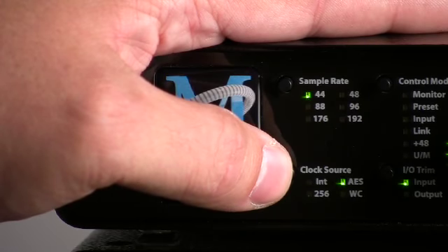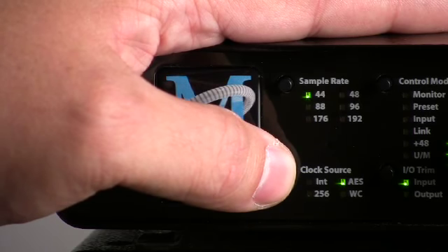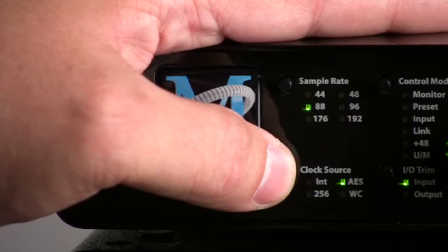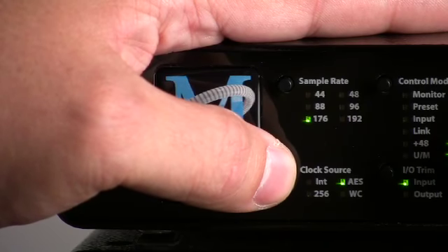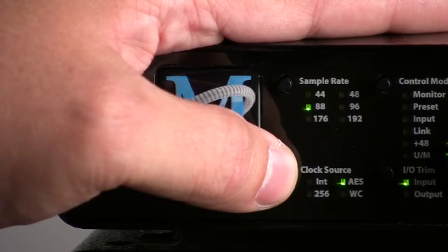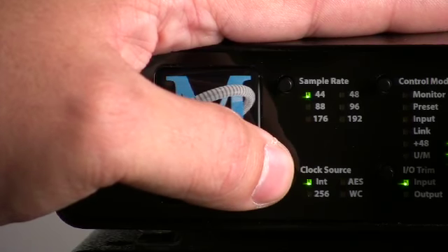AES is a bit different, since we not only have 3 different clock rates, but also have 4 different cable pairs to choose from. We have AES 1-2 at 1x, 2x, and 4x, 3-4, 5-6, and 7-8 until we come back to internal at 1x.